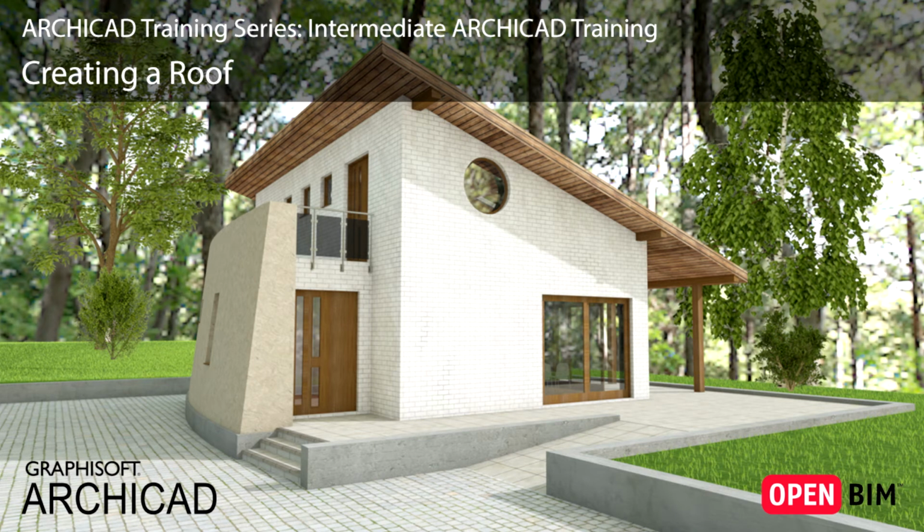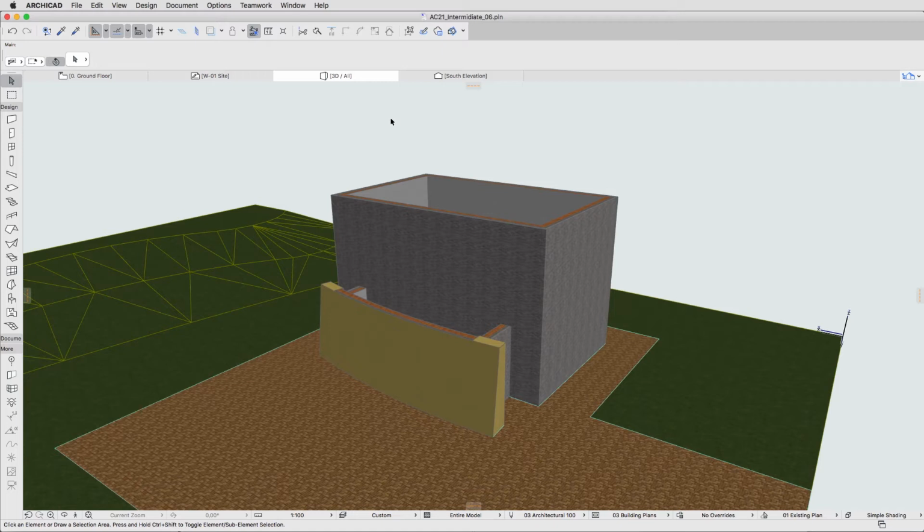In this lesson, we'll set up the existing stories and add one more additional story. Then we'll create a single plane roof and trim the walls under it. Our training project will have 4 stories: the existing ground floor on which we've already worked, a gallery and foundation that we will create now, and the roof.